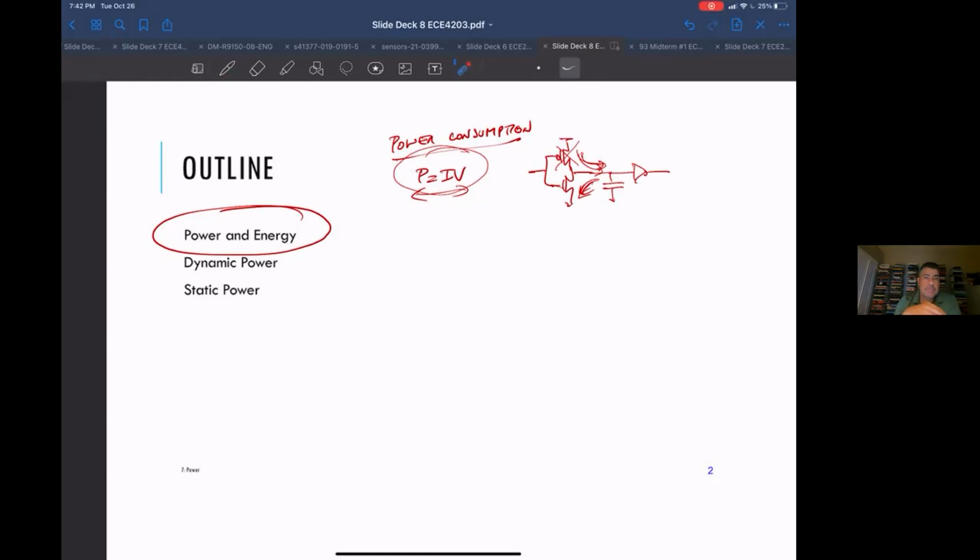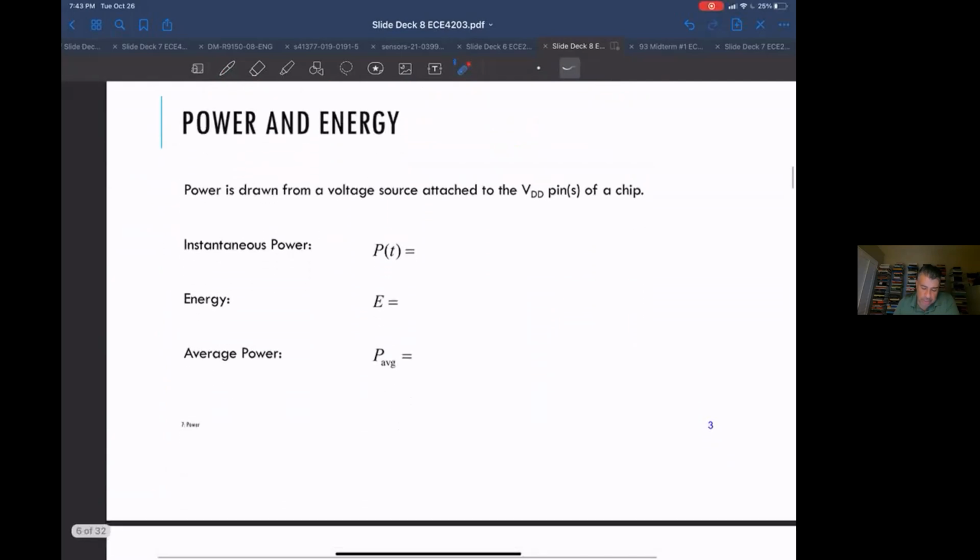That was enormously attractive compared to circuit families where there was power consumption even if you weren't doing anything. But with time, as we've gone to more and more density of transistors per chip, meaning smaller and tighter processes, the static power, which is the power consumption when nothing is happening, has also gone up. Unfortunately, now there is a significant amount of power consumption happening even when the circuits are not switching. We'll talk about that, and about some of the things you can do to help reduce that.